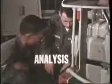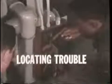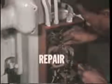Conduct a thorough visual inspection. Study the schematic diagram if it is available. Analyze the information that has been obtained. Locate the actual position of the trouble. Perform the repair.